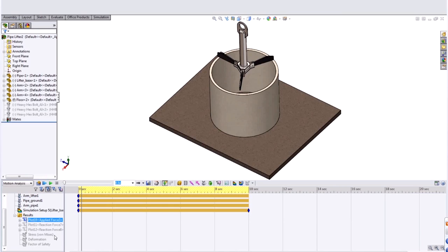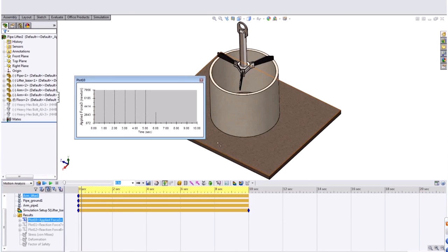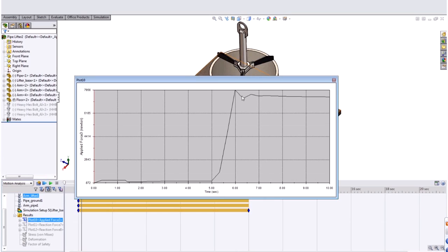The other approach we have is more of a manual process. I can look at this and say, well, my worst case stress or worst case load, pretty sure it's going to happen right around here, right? That's the peak in my load chart where the object's carrying the most load. That's going to happen at 6 seconds. As I hover over, it gives me that nice update there.